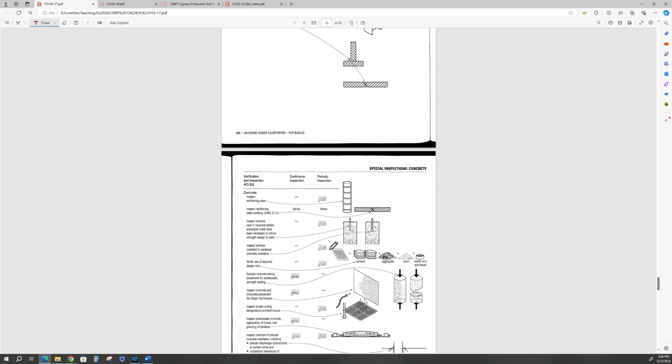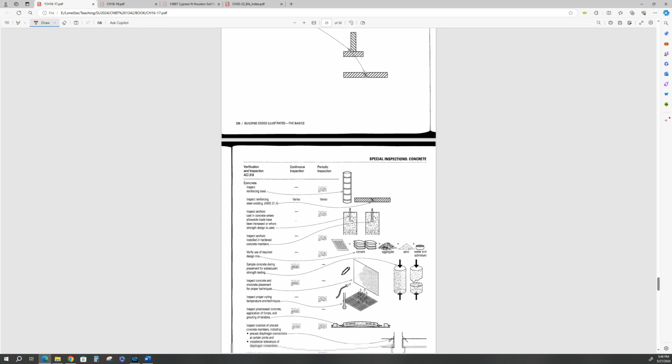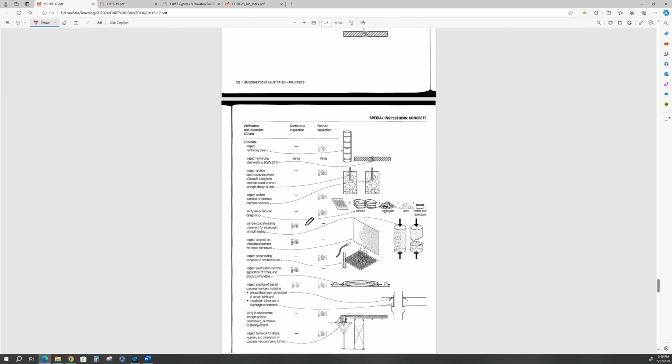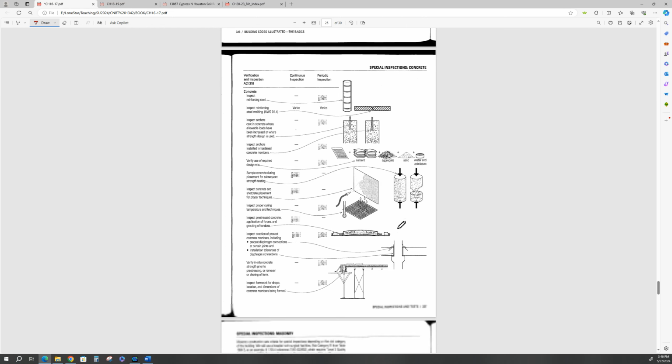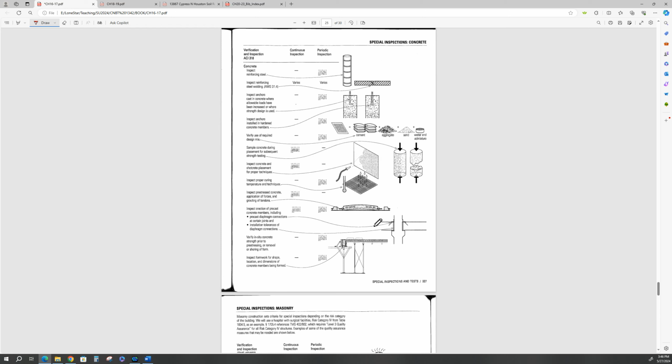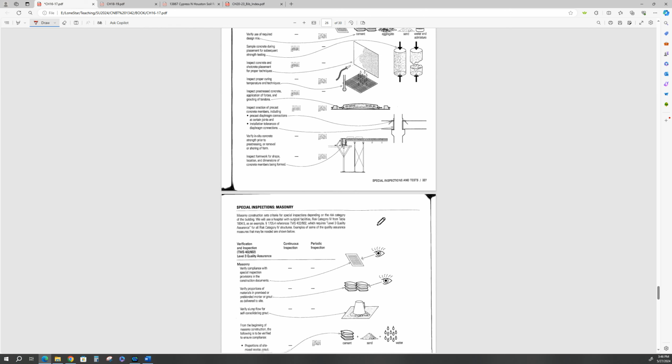We get the cement mix recipe from the concrete supplier. The structural engineer goes over that. Then we do the testing, water cement ratio, the 7 and 28 day test for the concrete. Okay. If it's pre-stressed or pre-cast, we get testing on that and inspection.